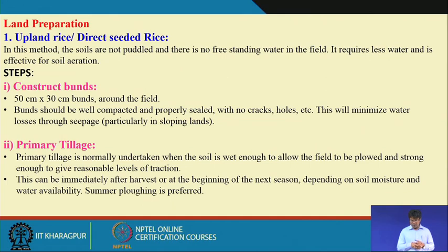Bund should be well compacted and properly sealed, with no cracks and holes there. This will minimize the water losses through seepage. It can store the water in the case of the upland ecosystem.